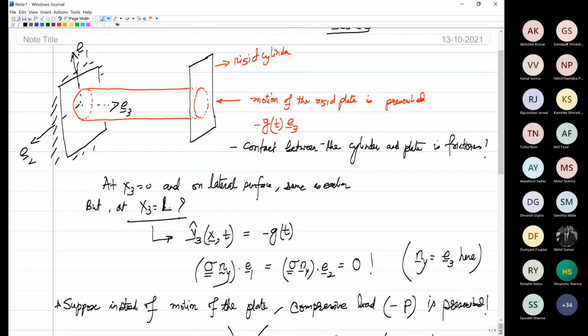It's very interesting. So as you push the plate with that load P, what do you think is going to happen to the area of the cross section over there? The points on the cross section there are moving radially outward. So the area of the cross section will not remain fixed. It's going to change, isn't it? And we don't know what is the current area.